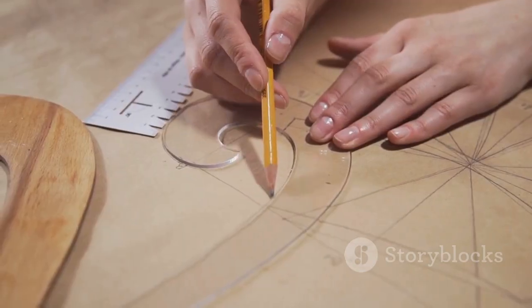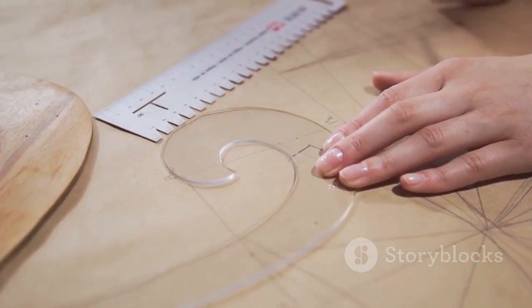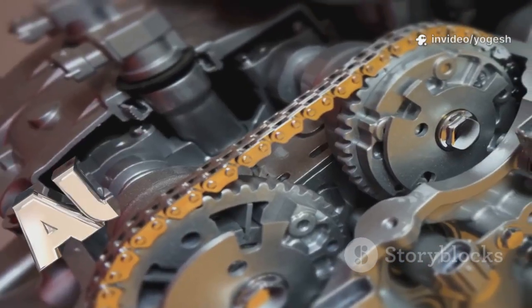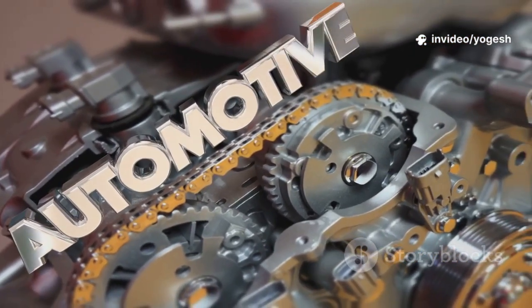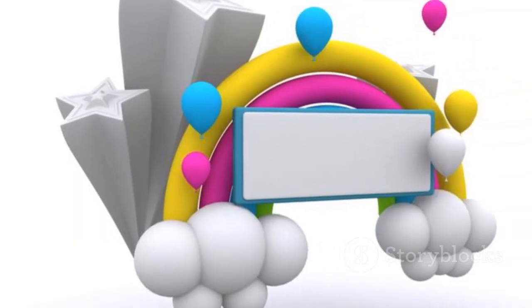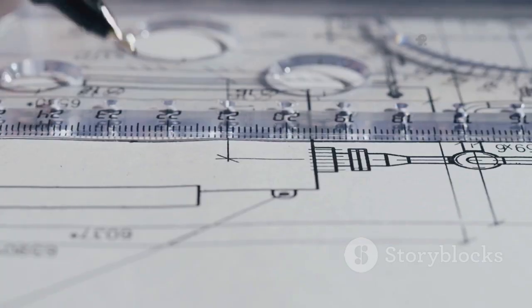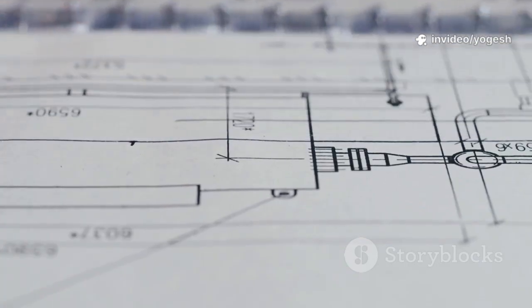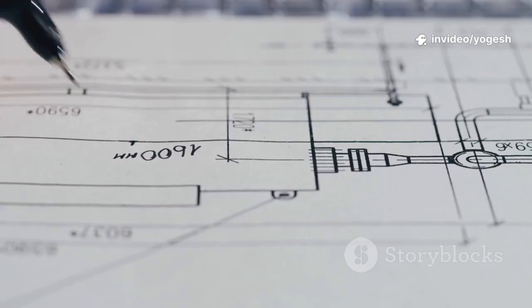Use phantom lines in your engineering drawing to indicate the paths of the V-belt and roller chain. These lines help visualize how power will be transmitted from the motor to the barrel, making the design easier to understand. Next, add balloon callouts that are linked directly to the bill of materials, or BOM. This step is crucial for keeping track of every component, from the smallest screw to the largest sprocket.